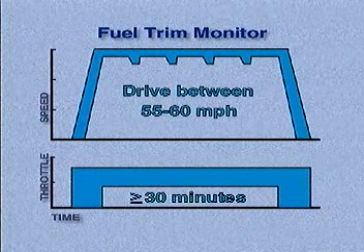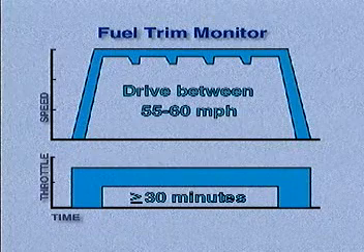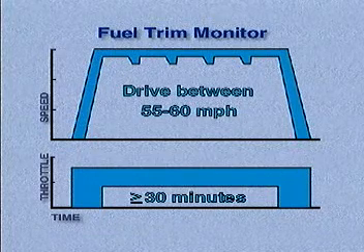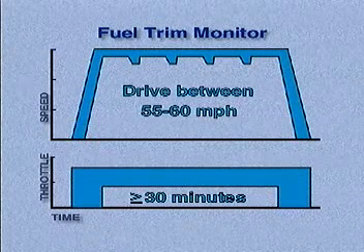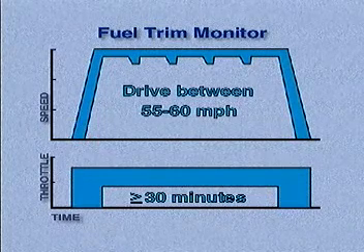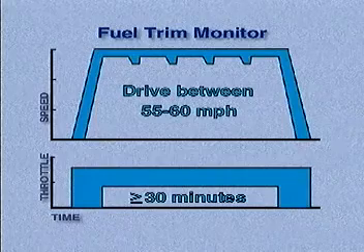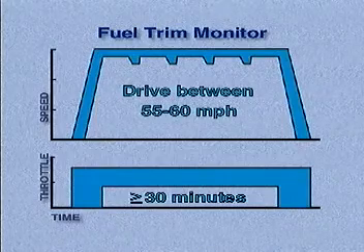During the test, you may apply the brakes, but avoid rapid accelerations or decelerations. When you are finished, verify a completed readiness test. This test allows the ECM adaptive memory to adjust to a steady and predictable set of driving conditions.